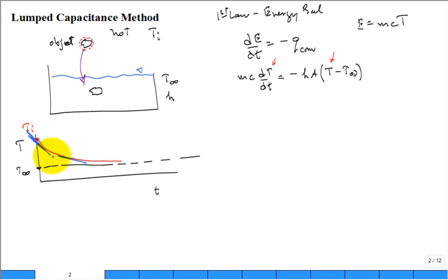All right, so I think we can manipulate this equation a little bit. dT/dt equal to minus hA over mc, or you could put rho V c, right? What's rho V c? Well, rho V is the volume times the density, that's the mass of the object. And then you have T minus T infinity. You could introduce, like the textbook, a temperature difference, theta.